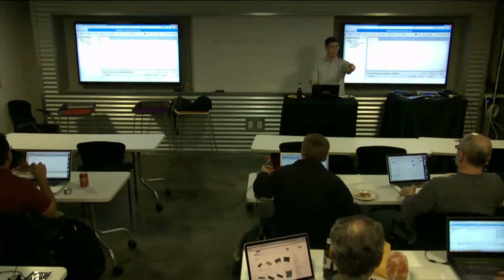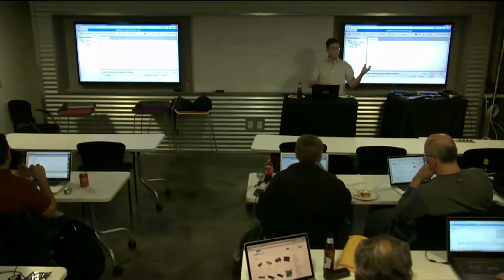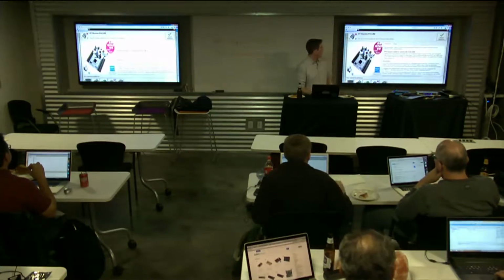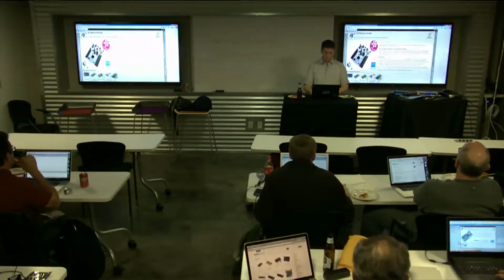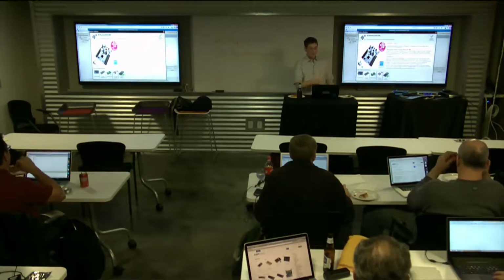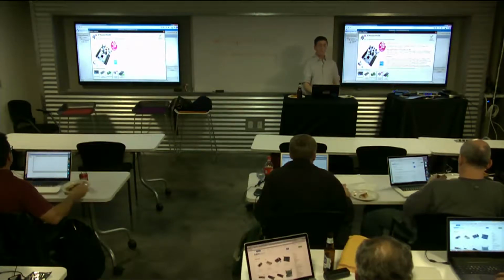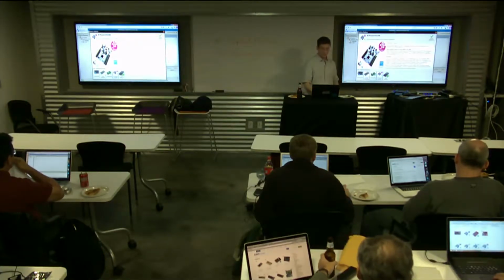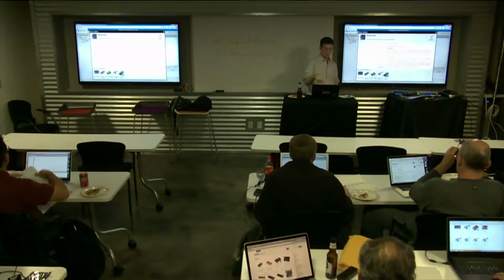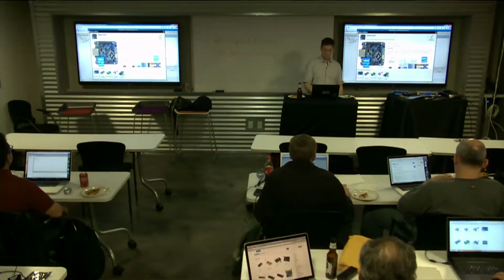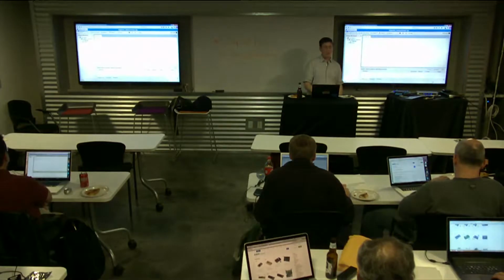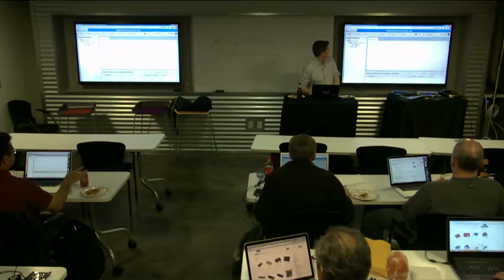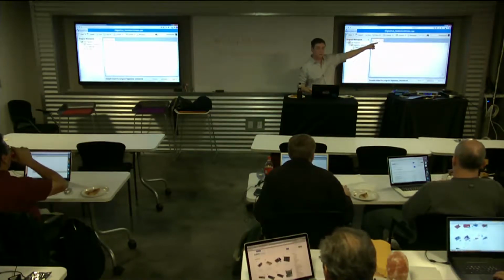So to your point, to change platforms, if I wanted to compile for one board versus another, I'd click up here in the top right-hand corner. And this is where I zoomed in too far, so this window is way too big. And this thing will pop up. These things I've got along the bottom are platforms that I've added on that first page, so I can change between any of them that I want. So I'm going to change to the K64F and select it. So now the top thing up here reads as the K64F. Yeah, see K64F top right corner?